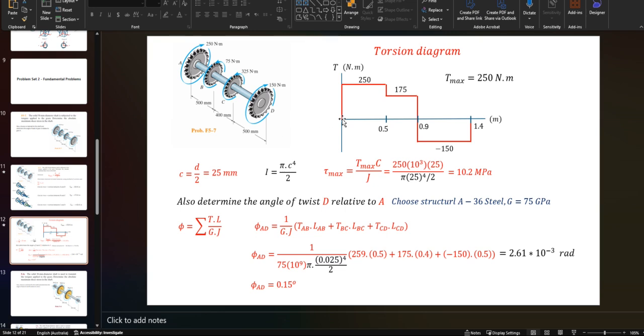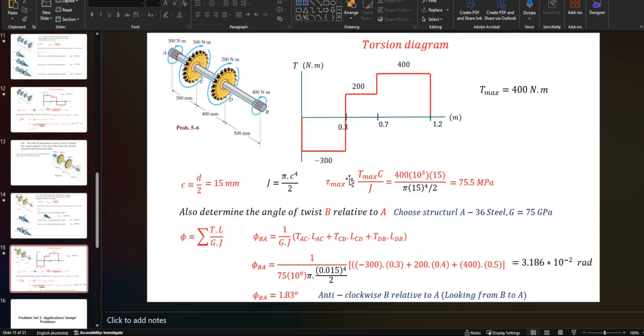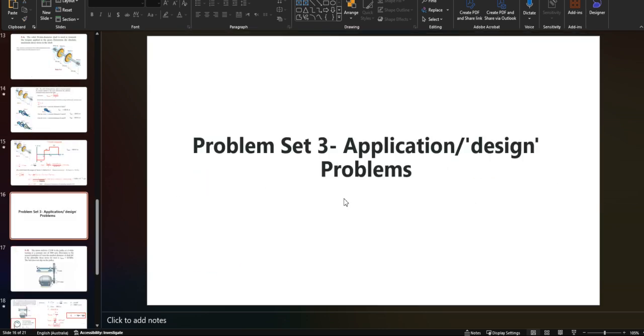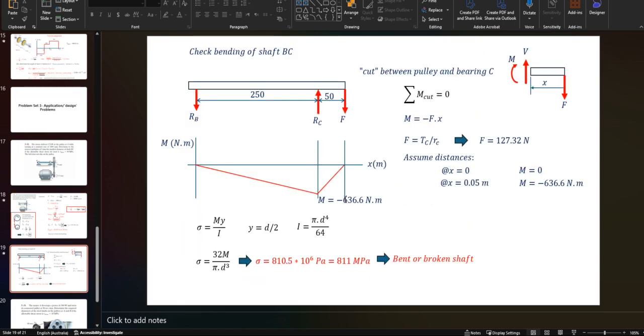You can see in this, once again, for the torque, we put in an input and we're going to get an output. So for example, this will be input, output, output, input. And the total at the end should be 0. That means that point A here has 250, and point D at the end is going to have minus 150. By getting this equation, we were also able to find an equation to calculate the minimum diameter, as we had here.